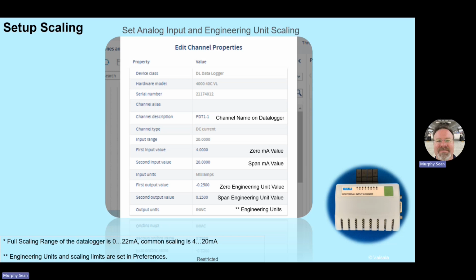So with the 4 to 20 milliamp, if you're getting a value that's 3.5 milliamps, it may actually correspond to an error code on the transmitter. If it's reading 0 milliamps, it means that you have no power in your 4 to 20 milliamp loop. So basically, any reading that comes in below 4 milliamps is an indication of a fault in the transmitter itself.